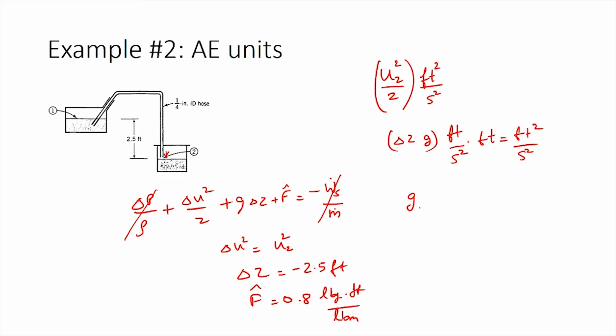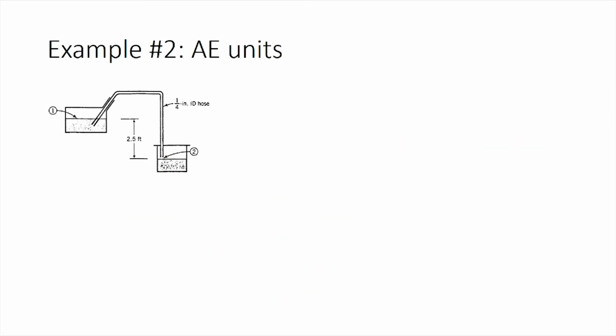If you remember the term conversion factor Gc, we know that Gc is numerically equal to the acceleration due to gravity at 45° latitude. So, this would be 32.174. If you remember the units, the units for Gc would be pound mass times feet divided by pound force times second squared. By using this Gc appropriately in each of these terms, we can convert all these terms to the same units.